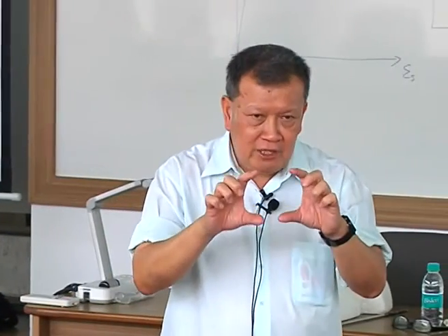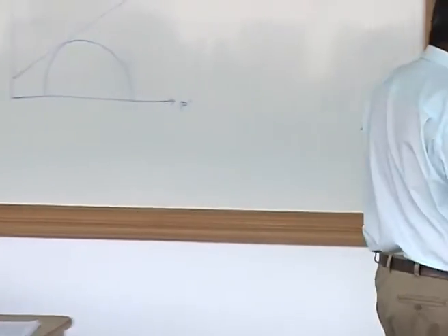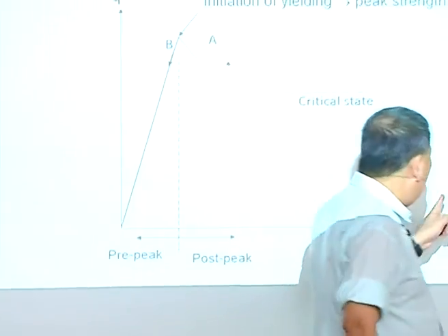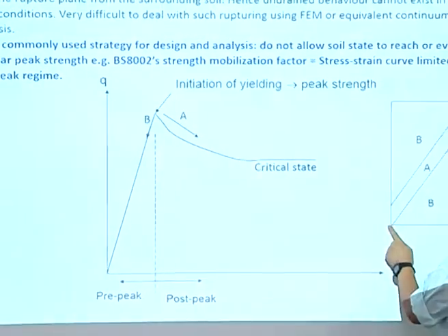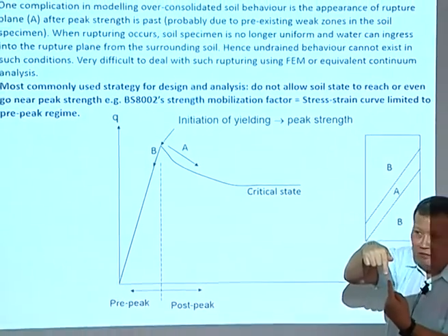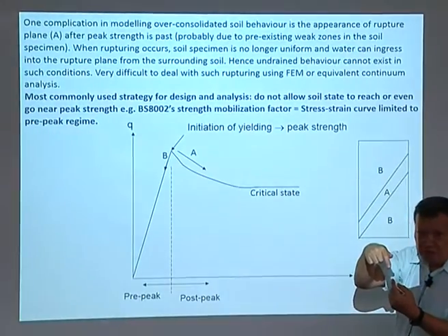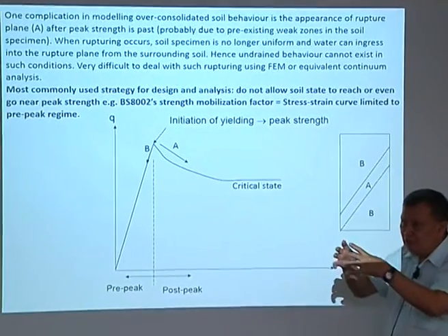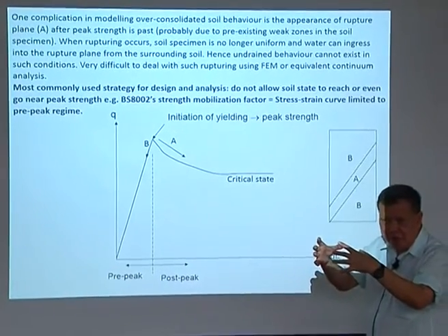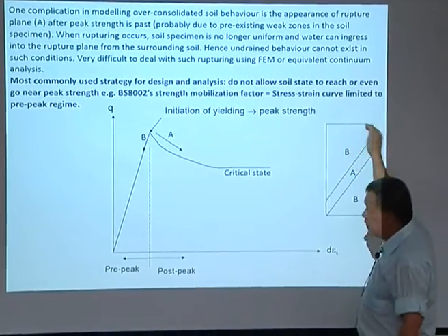The only way you can do it a little bit better is by doing this. You have a sample. One part of the problem with the shear band is that if you observe it properly, very often the shear band will arise from here or here. This is where the end cap will punch into the sample and cause a stress concentration. So the first thing is to use an enlarged platen.